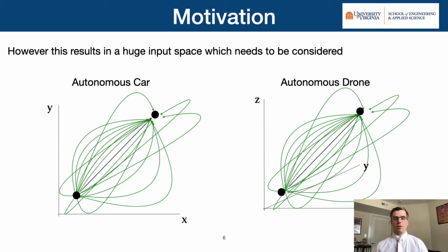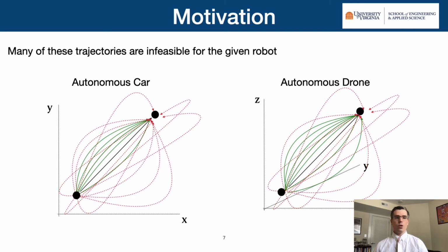For example, you might follow a straight trajectory between the two points, or you might take a curved trajectory between the two points. So the first question you might ask yourself is, which trajectories do I want to use as a system test? While trying to solve the first question, you'll realize that many of the trajectories between the two points are infeasible. They cannot be physically achieved by your specific vehicle. Thus, for each test, you need to consider your vehicle's physical abilities carefully.